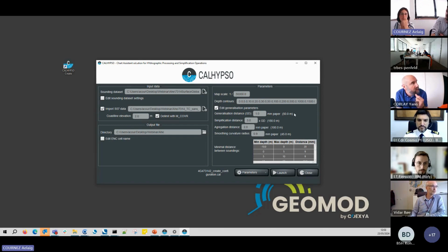But that's why the experience of the cartographer will always be needed. You know your place. You obviously know your coasts. Therefore, you might know which input parameters might be needed in order to make the generalization satisfactory. For example, as Yves said, our rocky coasts in Brittany are not the same as the ones we can find in the overseas territories in the Pacific, with undersea pits, while here we have simply shallow depths, which are not so problematic to treat. But this obviously needs your experience. Once you find your own settings of parameters, you can go on with some similar areas. You will have your chain running.